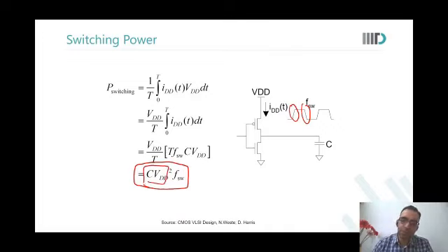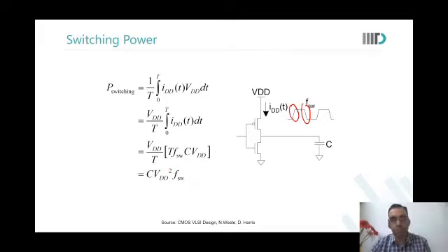Are you able to see this? Sir, so this becomes the average dynamic power dissipated. Average switching power, not dynamic power. Dynamic power will also have short circuit current in it. So, sir, this is what we have to do in our assignment, right? Yes, you have to do this average power dissipation. You have to also include the short circuit power in it.